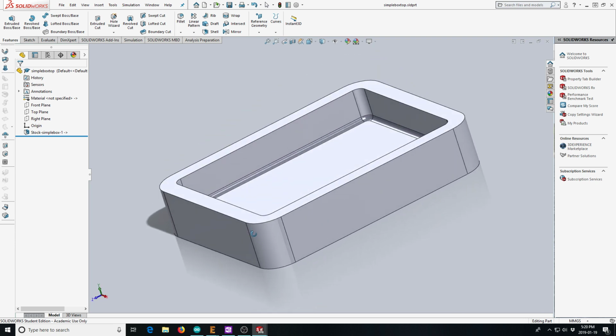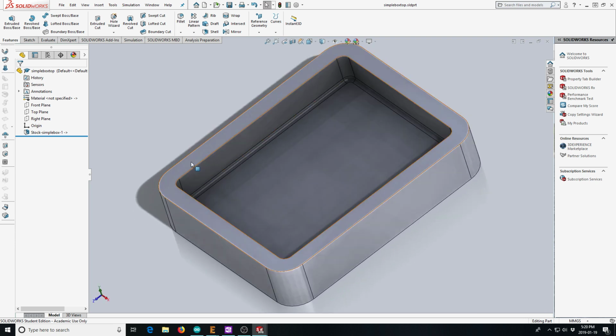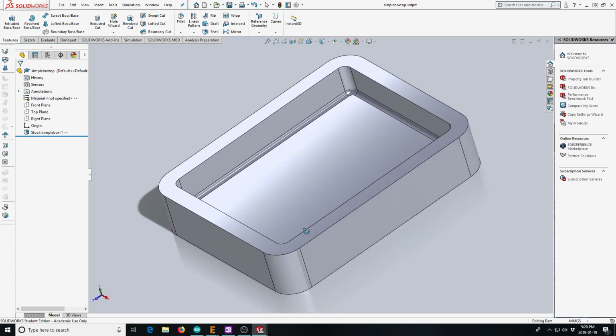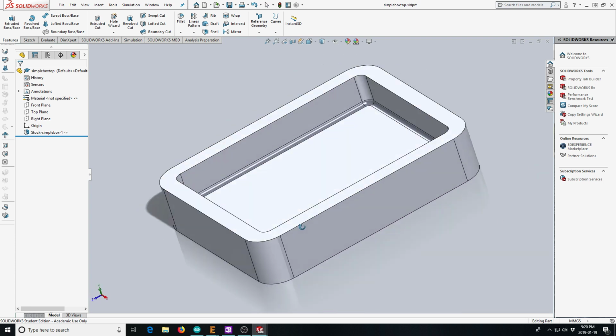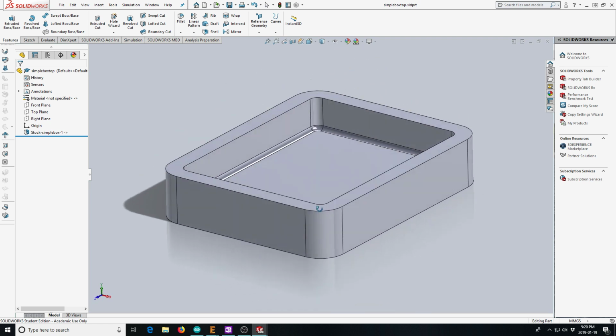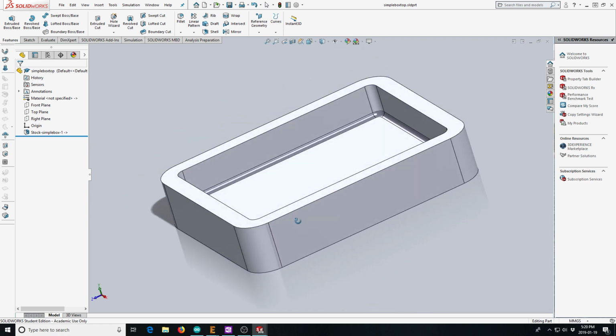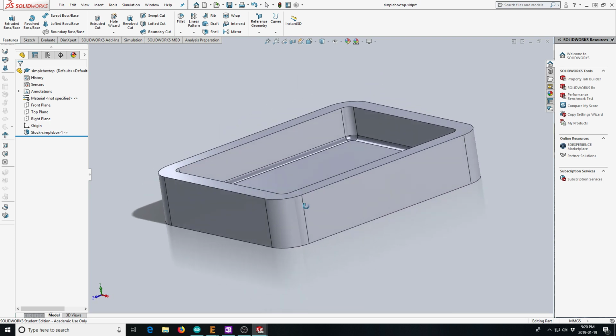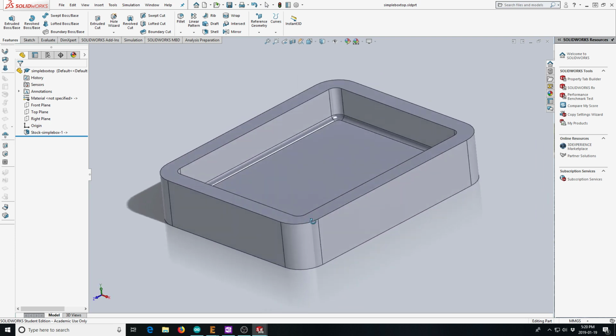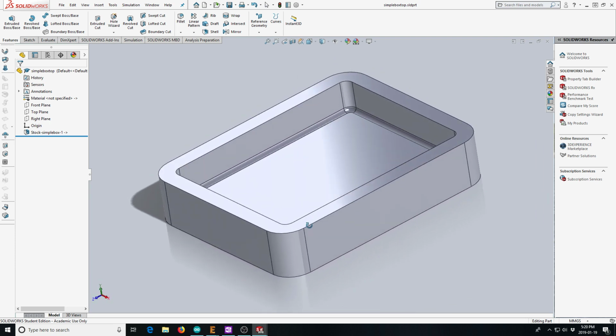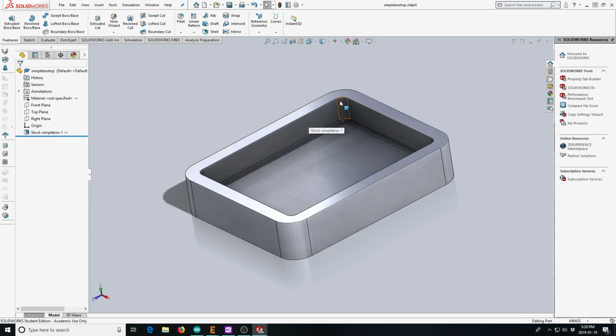Now, if I were to take these and make them, they just have two flat surfaces. And they're not going to hold together very well. They might have the same outside size and everything like I've made them, but perhaps I'd like to actually have them somehow interlock better. So I'm going to make some cut features on this mating face so that the box will actually fit together.